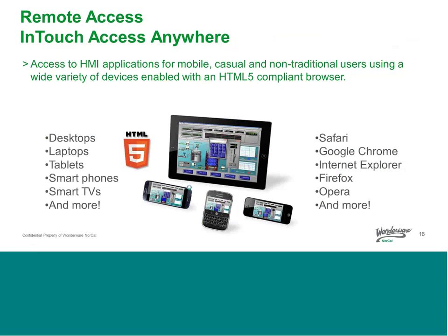Moving on to remote access. We'll be doing a demo on the situational awareness and the remote access here in just a moment. We get a lot of requests now for mobility. Can Wonderware run on a web page? How do I get Wonderware on an iPad? How do I get Wonderware on my Android phone? How do I make it easy for people to access my SCADA system, maybe in a read-only environment or in a read-write environment where I actually want to change a set point, turn something on or off?